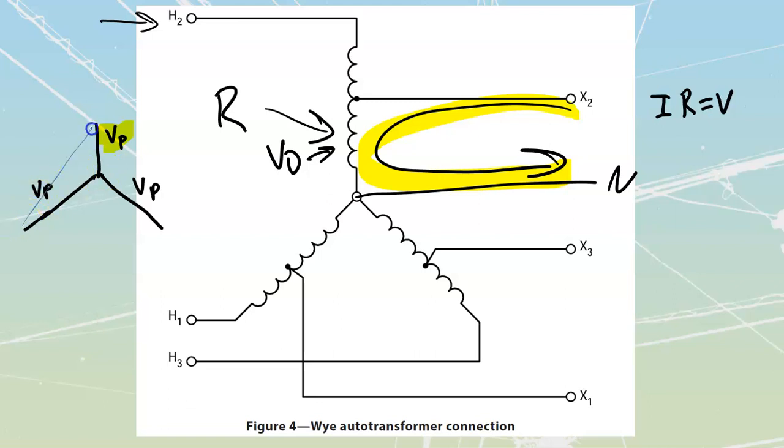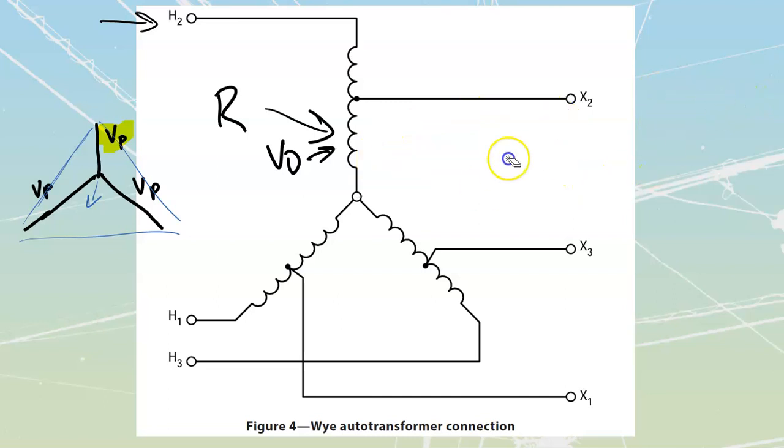First of all, my line-to-line values of voltage are going to be unequal. Secondly, my neutral current is not going to completely cancel out. I'm going to have actual neutral current, and it's going to be out of phase as well. So we're going to get just a pile of different small issues with it. We're not going to use this where we know that we're going to be intentionally supplying single phase loads. We've got another transformer coming up for that. We'll take a look at that one a little bit later.